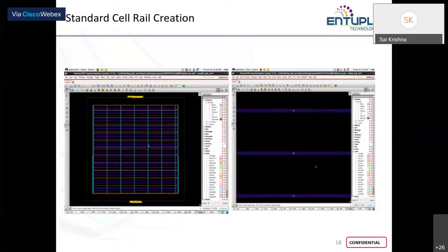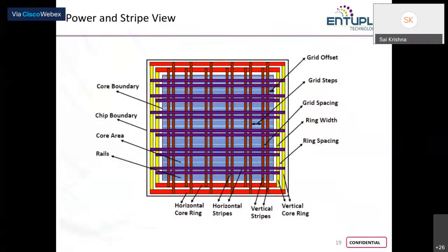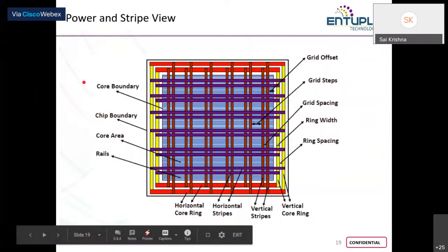So that is why your standard cell height and standard cell row height are exactly the same, and every cell will never cross over any of the standard cell rails after being placed. Okay, so this is the strip view. You can have a look at it for a moment. All the spacing and widths shall be explained to you during your demo part.